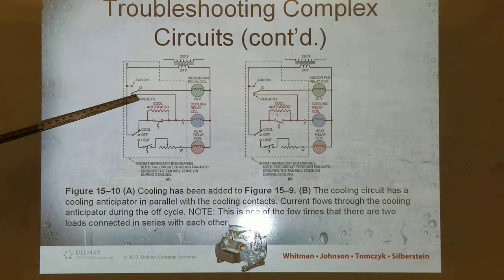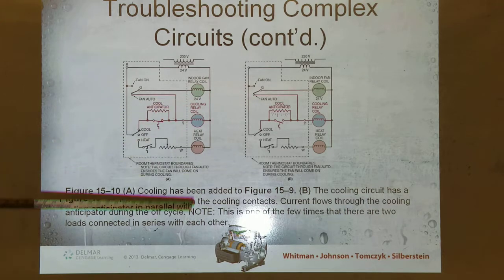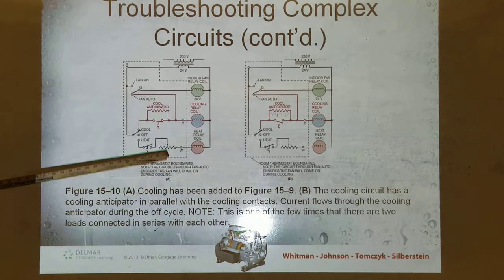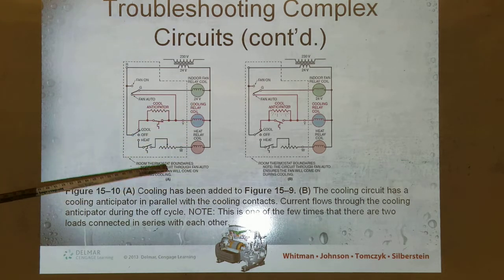goes back, goes through the fan switch, and it energizes the indoor fan relay coil. You seeing that? So that's what makes that fan turn on when the cooling turns on.